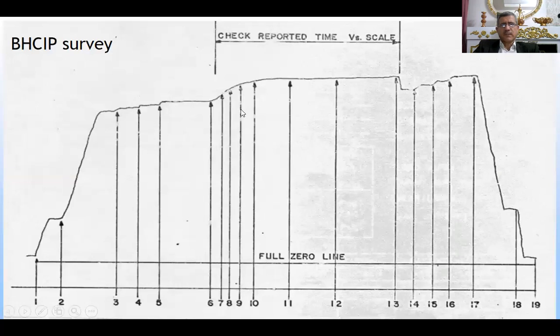You see here, the SCIP, we can obtain the reservoir pressure. We stop for 2 hours. After closing the well, we run a gauge, a memory gauge, and in this case, we can measure the reservoir pressure. It is called bottom hole closed-in pressure survey.